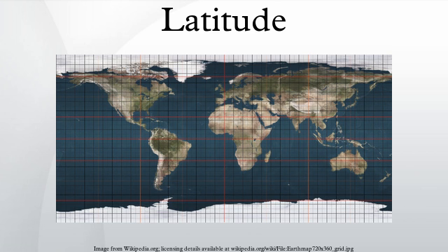Geodetic coordinates. At an arbitrary point P, consider the line PN which is normal to the reference ellipsoid. The geodetic coordinates (φ, λ, h) are the latitude and longitude of the point N on the ellipsoid and the distance PN. This height differs from the height above the geoid or a reference height such as that above mean sea level at a specified location. The direction of PN will also differ from the direction of a vertical plumb line. The relation of these different heights requires knowledge of the shape of the geoid and also the gravity field of